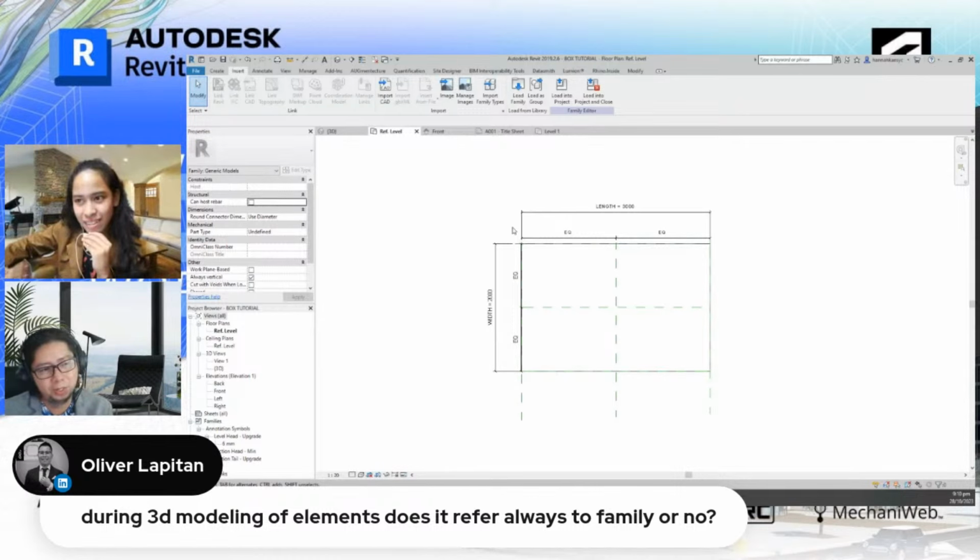It won't be out of place, unlike when you have the drawing and then insert a CAD file. The CAD file doesn't do anything good if you insert the CAD file or a 3D CAD model, so it is better to create a family first and then insert that CAD file in the family.